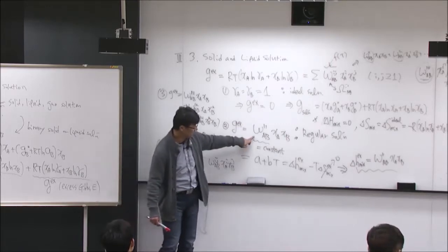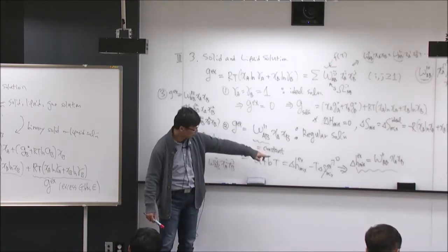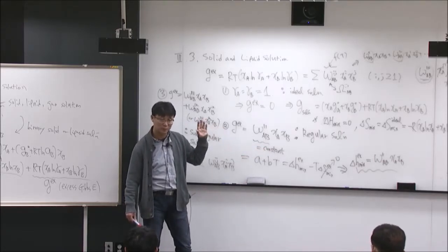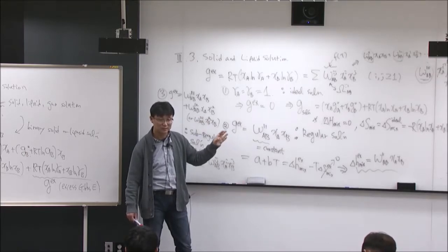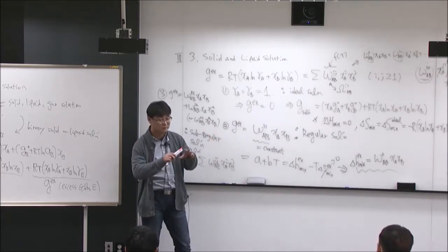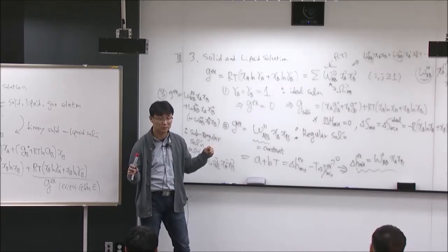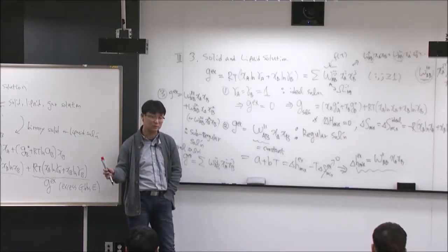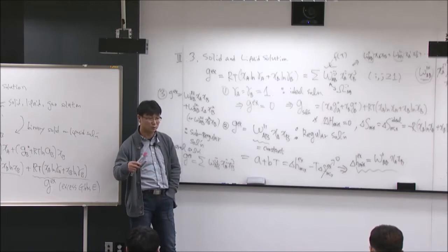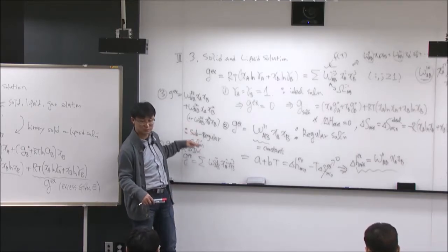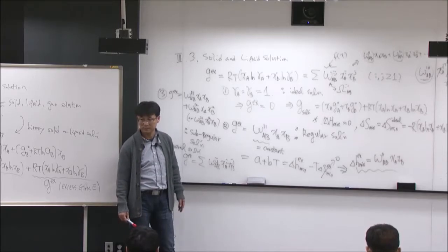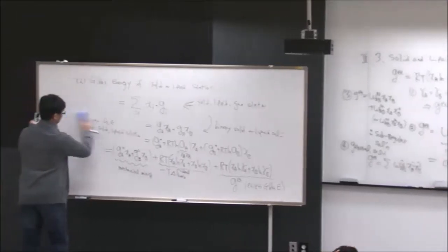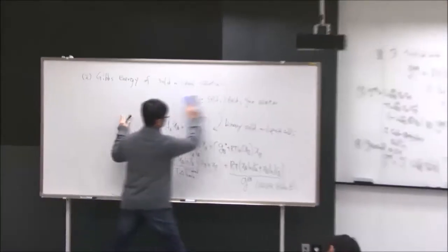But if this is not constant, for example A plus BT, then you could also have excess entropy of mixing. Specifically, when you say regular solution, that is not a regular solution. Some people call it a regular solution, but by definition it is not. A regular solution only has excess enthalpy of mixing, not excess entropy of mixing. And if you want to make this more complex, then we could have subregular solutions, and so on. Let me show you this expression in a graph, then you're going to understand more.